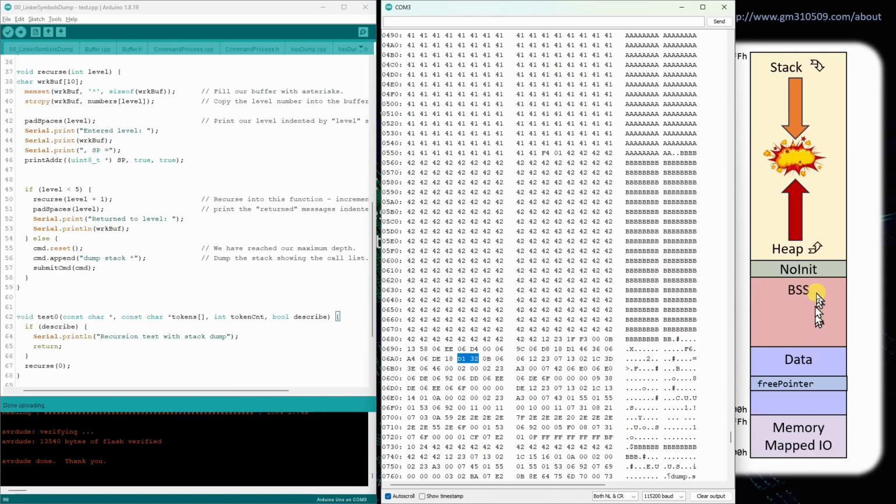And if we lower this line, well, I guess this no init line, but since this always seems to be 0, it's basically the same line as the BSS. If we can lower this line as much as possible, then we'll give more space to the stack and the heap, because it just uses whatever memory happens to be left over after these things have been allocated.